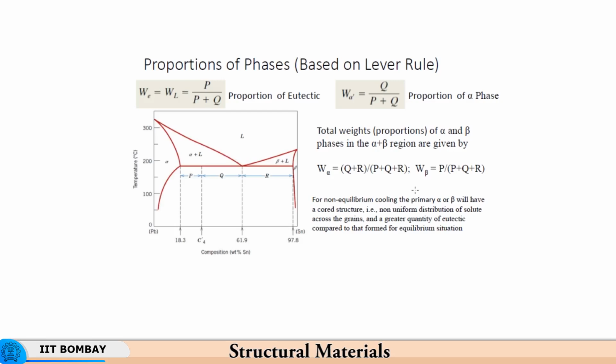So, there is an entire solidus line, and on the other side of the solidus line there is complete solidification of the liquid portion. So, here alpha is already solidified, liquid coexists with alpha. So, these two phases coexist, and this liquid gets transformed to two different phases. One is, let us say, a solid solution, and the other one is a eutectic.